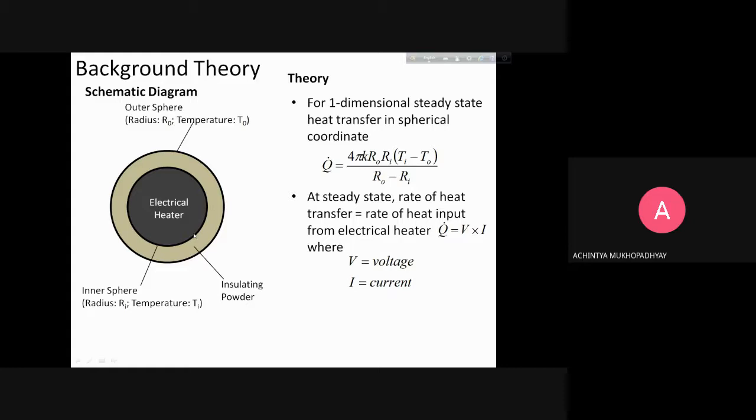By putting metal surfaces, we ensure very small temperature variations, because with high thermal conductivity, even if there is some non-uniform heating, the resultant heat flux will not cause any significant temperature difference.